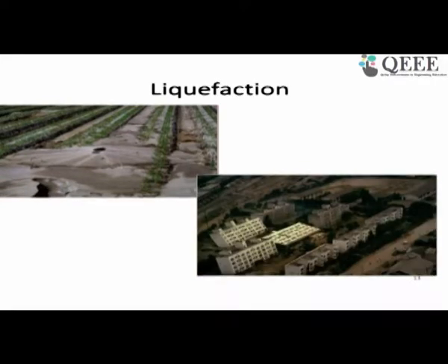During an earthquake, some soils, especially granular soils, liquefy or lose shear strength in some specific situations, and the superstructures resting on those soils may collapse. So that kind of site or soil needs to be investigated before we go for the design of any structure on that site.